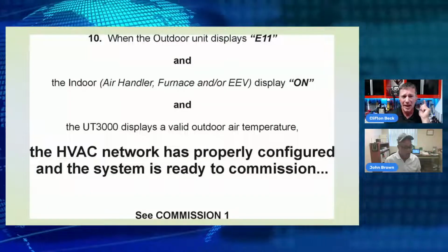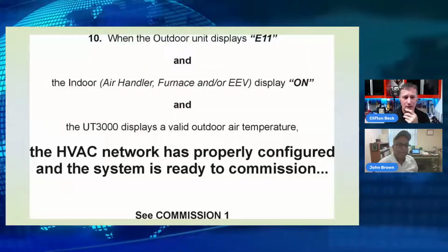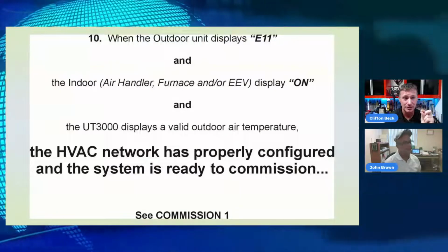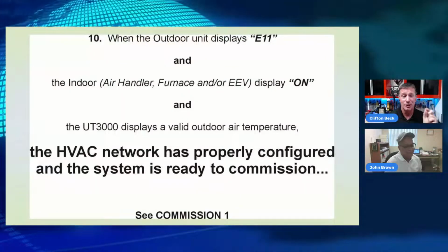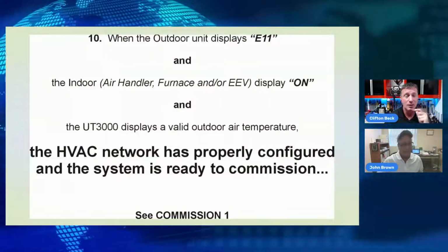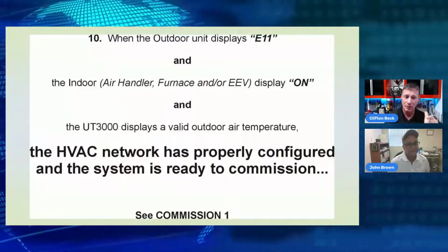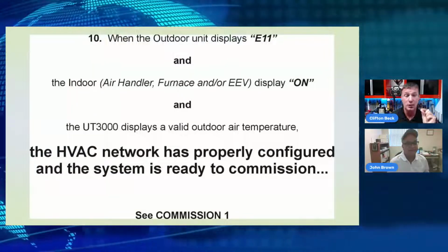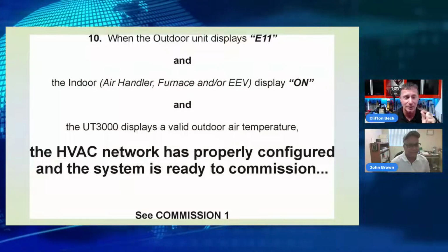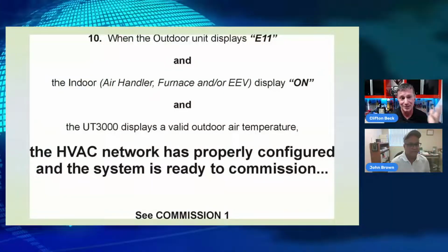Okay. A lot of people ask about that. They'll say, do I have to add an outdoor air temperature sensor to this if they first get that code where they're not reading an outdoor air temperature sensor? And for those people who are familiar with the older Honeywell CTK series and the Honeywell communicating systems, the Prestige, where you can add outdoor sensors, a lot of people ask, well, do I need to add that? No, we are utilizing the outdoor temperature sensor of the outdoor unit. One of the many sensors and thermistors that we have on our new inverter technologies.